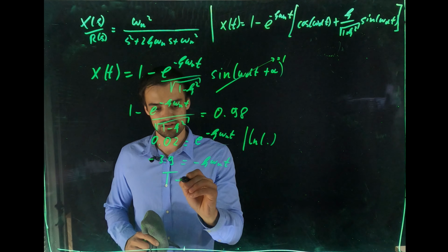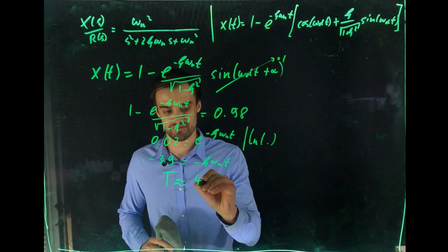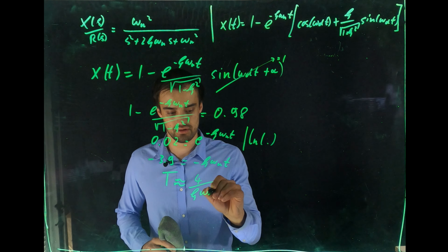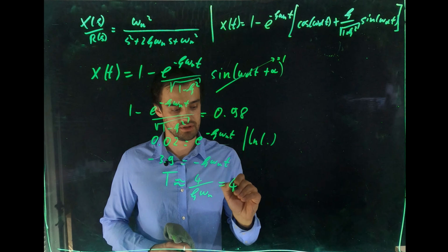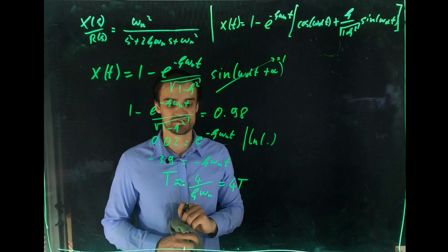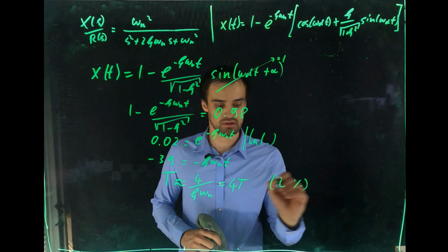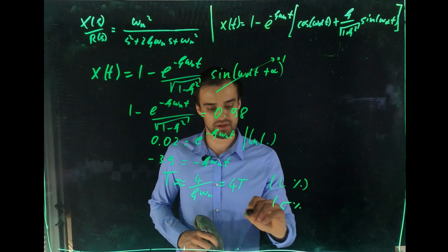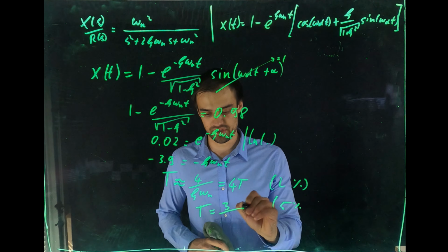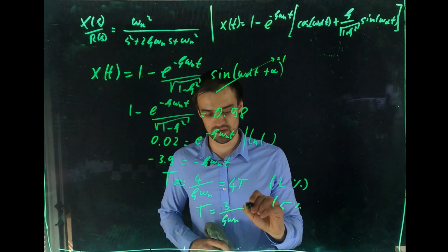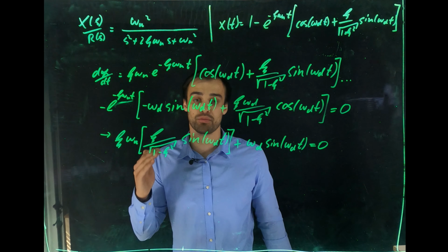And voila, the settling time t_s is nothing else than approximately 4 divided by zeta omega n, and this is equal to 4 time constants. The same can be applied for the 5% rule settling time. For the 5% rule, t_s is nothing else than 3 over zeta omega n, or 3 time constants. Next, we talk about the peak time.